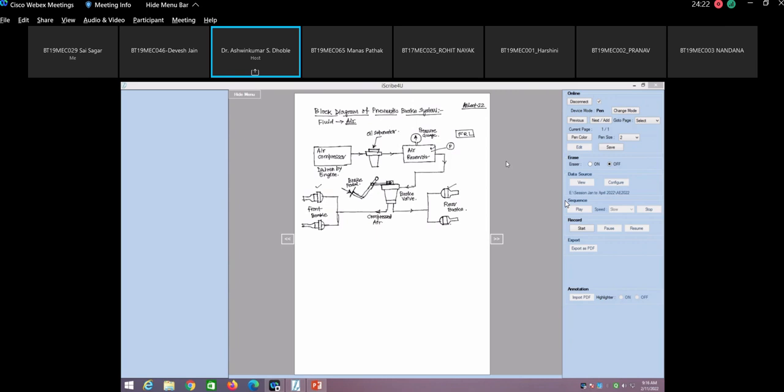By that time the required pressure may not be reached, and that may cause the brakes to not work when you drive initially if there is no air reservoir. So the air reservoir is a must, because you need to have the supply of compressed air, or air under pressure, every time, whether you start the engine or not. Such a requirement has to be met, and that is why the air reservoir is used.